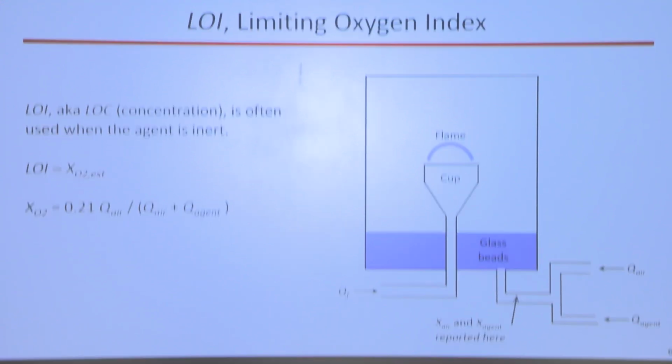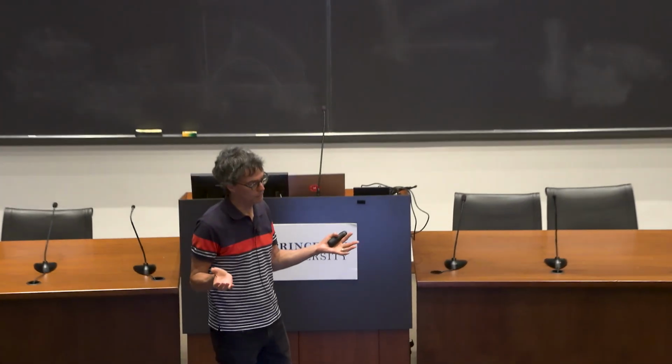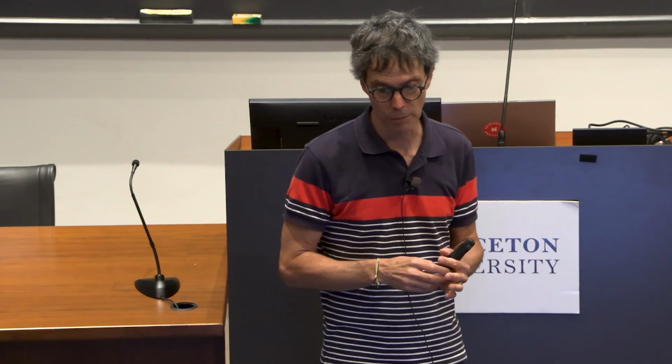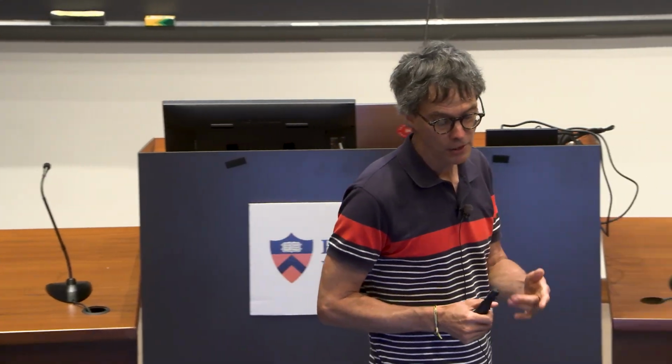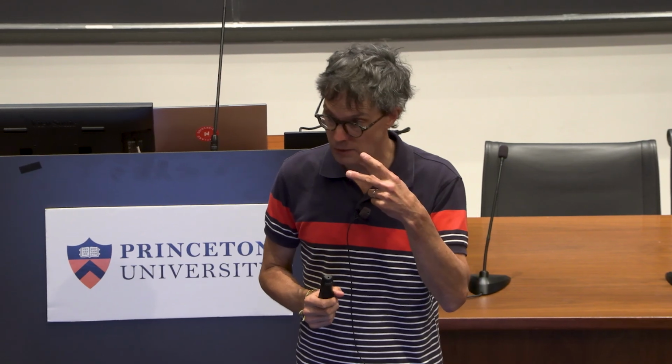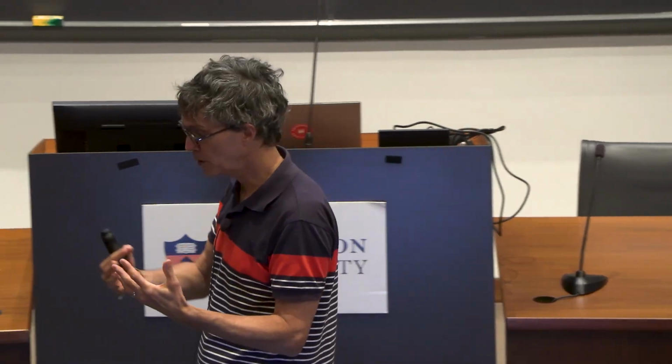And that gets reported out two different ways, but they're equivalent. There's the LOI and the MEC. And there's just a simple expression relating them. LOI stands for limiting oxygen index. And the idea with this is that if you drop your oxygen concentration down to about 15% mole fraction, almost nothing will burn. So there's a video here, I'll give the link at the end if you want to see, where someone's actually smoking a cigarette and walks into a room that's at 15% oxygen.